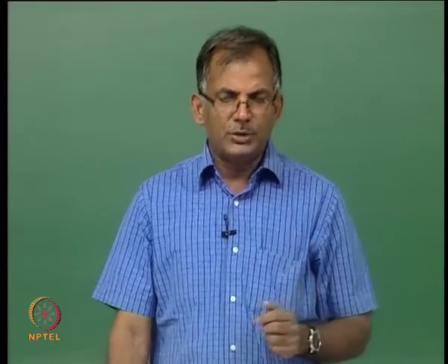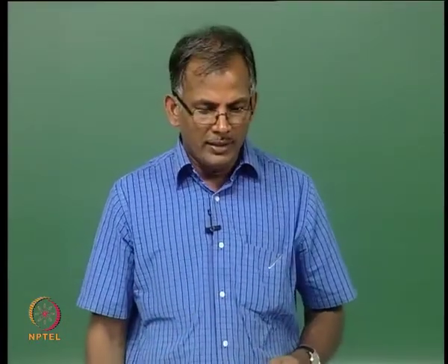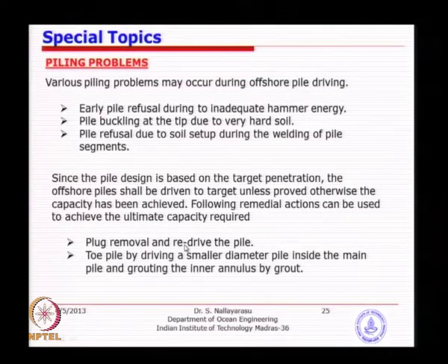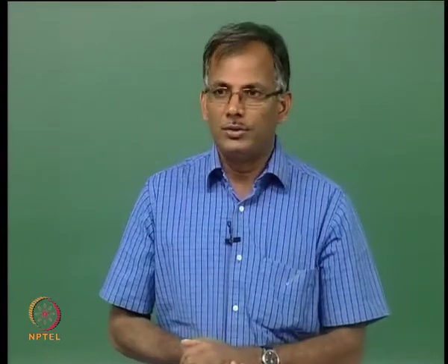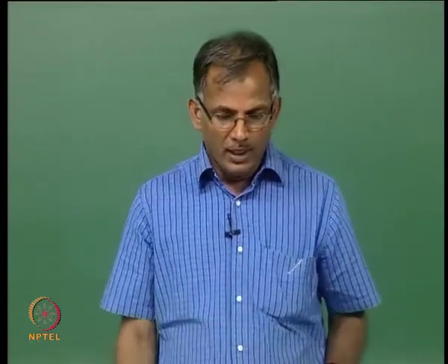If you have such issues on site, think about how you restart. One idea is removal of the plug. You remove the soil within the pile somehow. What happens is the internal resistance is removed, the pile end area resistance is removed. So when you restrike, the resistance is reduced, so the pile can actually go down. That means you need a machine which can remove the soil, which is called relief drilling. So you have a drilling machine on board. While going offshore you only had a driving machine, now you have an additional drilling machine. If you have a drilling machine, I think you should not have a bigger worry. Only thing is, if you don't have it, this cannot be done.